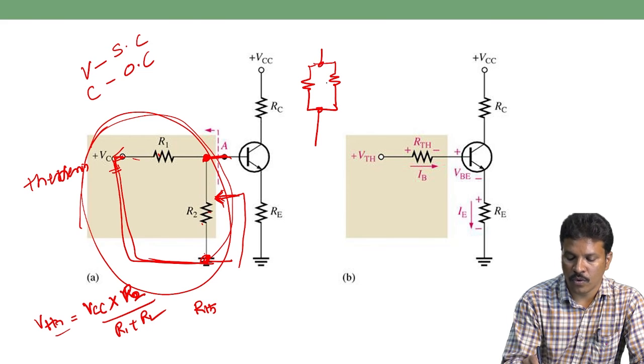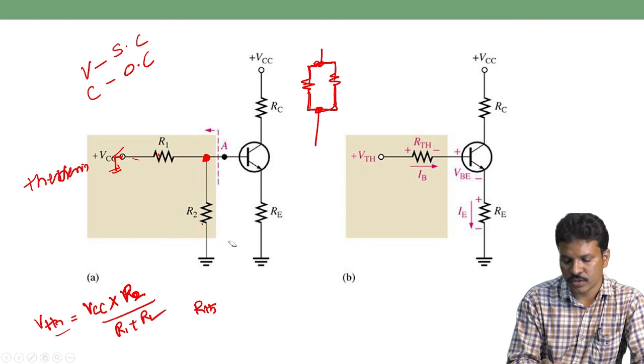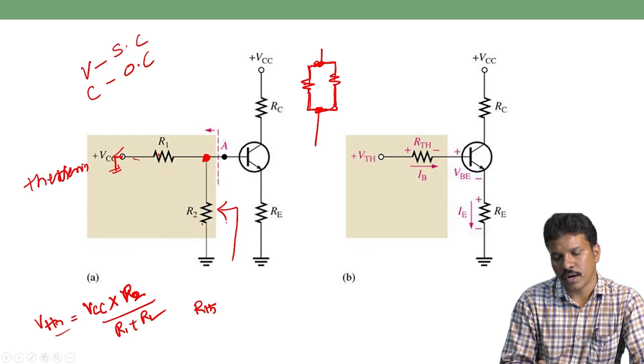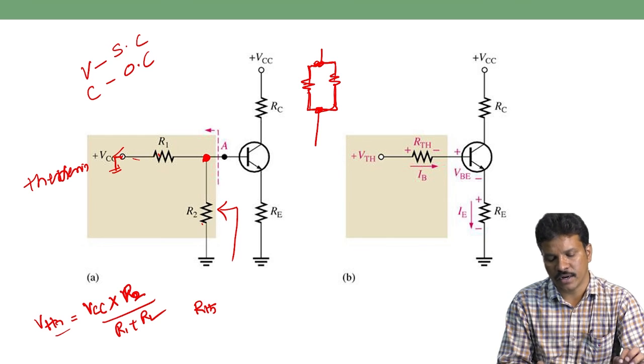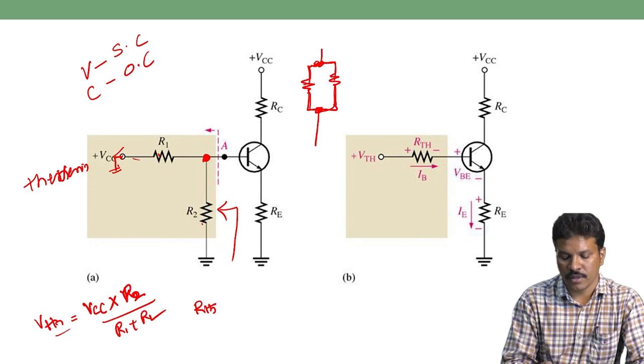Okay. Two resistors have one end joined at a common point, and the other ends of the two resistors are also joined at another common point. Then they are said to be in parallel. So when we look into that network, shorting the DC voltage source and opening the AC current source, then measure the total resistance. They are two in parallel.